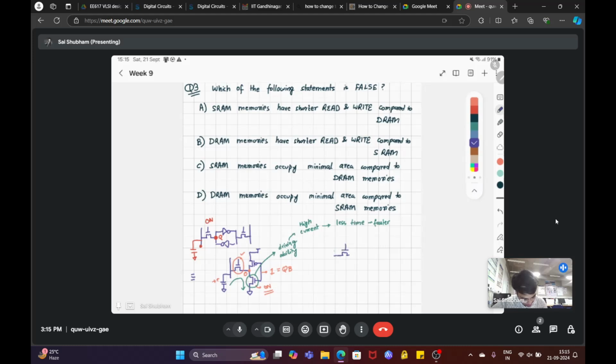There is an access gate transistor, you have a huge capacitor, and you have a small capacitor over here. Okay. So now when this transistor is on, suppose VDD is stored over here. Okay. And it has some charge, it has some capacitance CD, and this is the output capacitance, output load. So suppose it is discharged to 0. So finally the charge will be (CL plus CD) into V equal to CD VDD, or V equal to CD/(CL plus CD) times VDD.